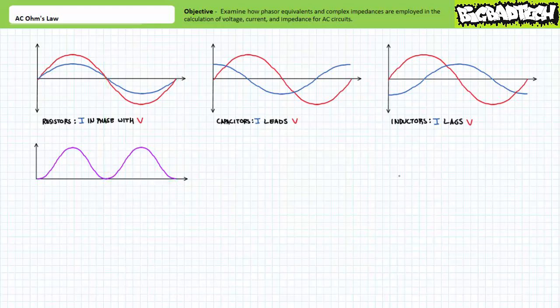For a single complete cycle of a sinusoidal AC voltage waveform, the resistor would experience 2 bursts of positive power dissipation. Note that 2 bursts of positive power dissipation can be averaged to arrive at an average power dissipation figure over time. We'll return in a moment to discuss the significance of this observation.